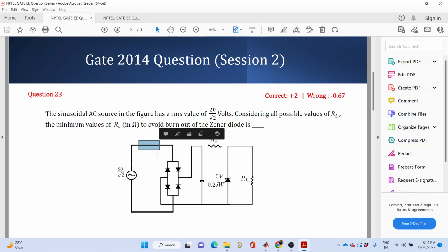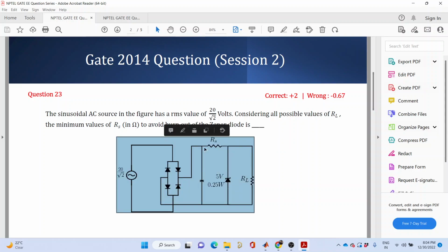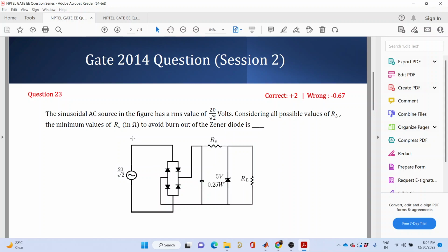I'm putting a resistance in series with the voltage source at this point where I've made the block, and connect a switch in parallel to it. The moment the capacitor is fully charged and has gone into steady state, we turn on the switch in parallel with the limiting resistance, so that we do not have much of the losses and we get the voltage that we want. That is one thing. Any other solution that you can suggest?